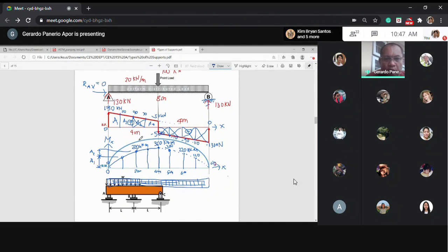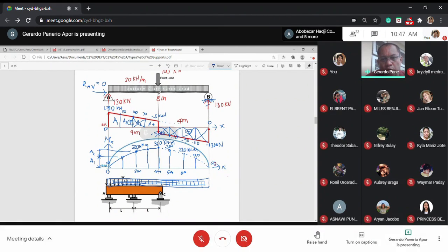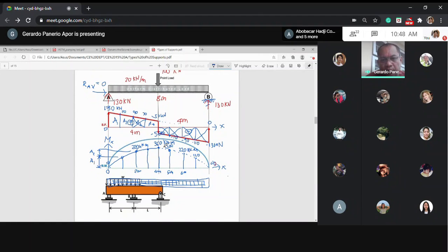So you need the reinforcement where the critical force is. The critical is here, maximum. In fact, if you load it to failure, it will start at the maximum moment and at the maximum shear. So that's why you see a lot of cracks here if the beam is not reinforced well. You see a crack here because you have maximum shear. And also you have flexural cracks here because you have maximum moment.